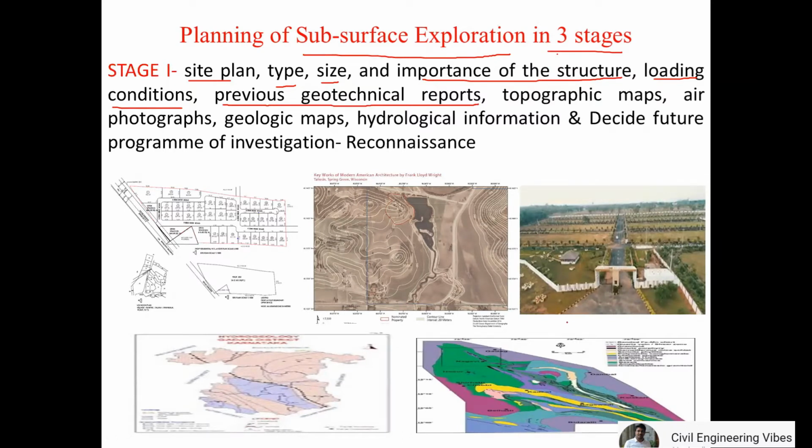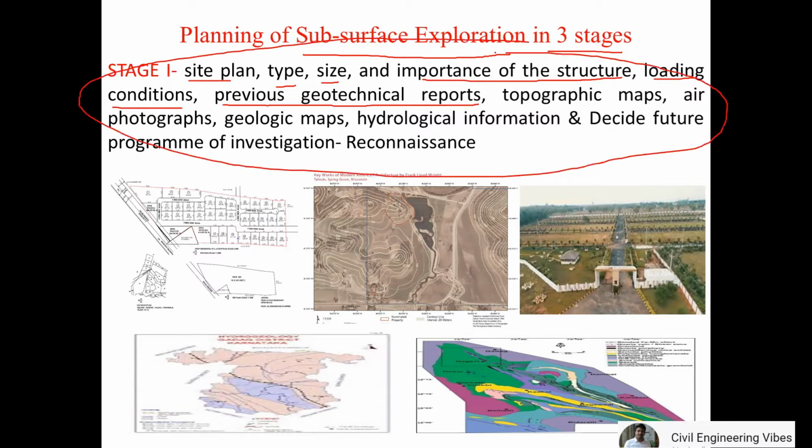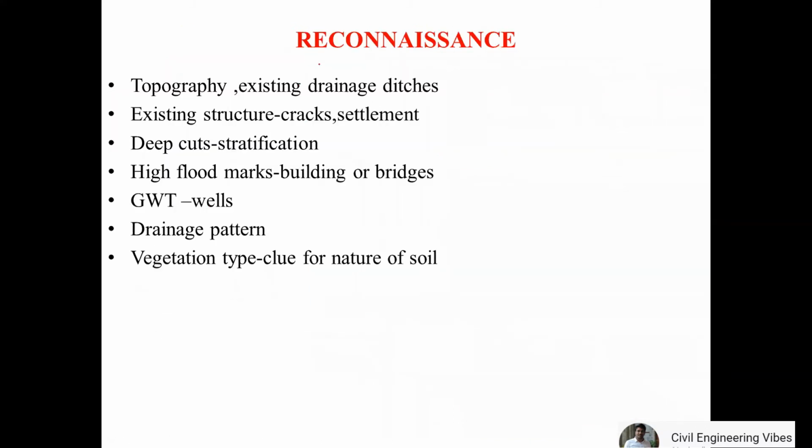This is all about the examination of the already existing data about the soil and geological conditions of the site. The existing local knowledge comes from observing the behavior of the existing structures in the vicinity. That will be very helpful. The exploration should be preceded by site reconnaissance. What is meant by reconnaissance? It is the observation of a region to locate certain strategic features. These are the observations to be made after visiting the investigating site. We'll go on one by one in detail.